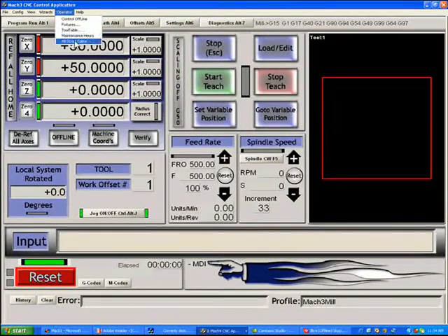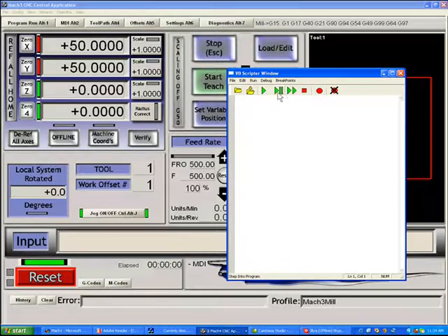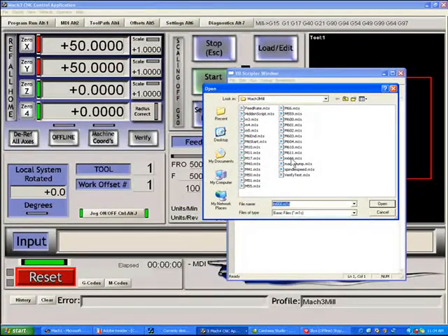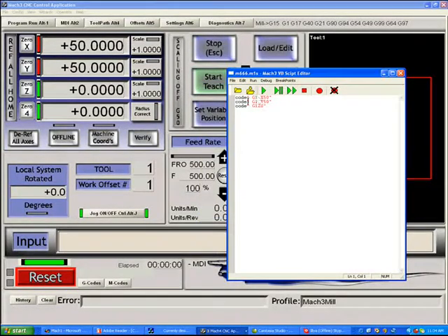You've got the Visual Basic scripter. Remember that you can single step through codes, load and get rid of them. Let's take a look at another code here. Let's go back to our famous M666. You can see if I click on the second line and hit the red button here, which down in the status line will show toggle breakpoint, I can actually run this code and tell it to stop when it hits that line.